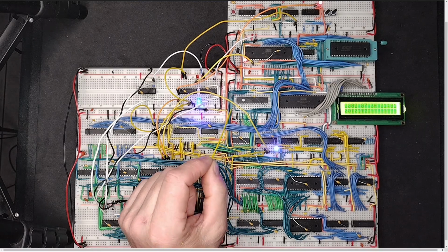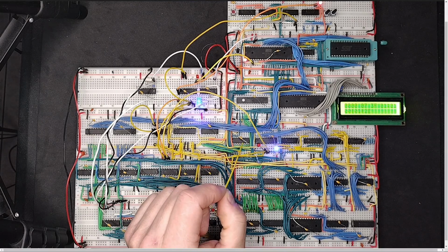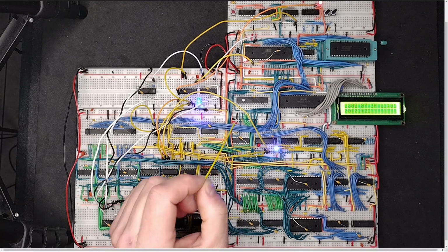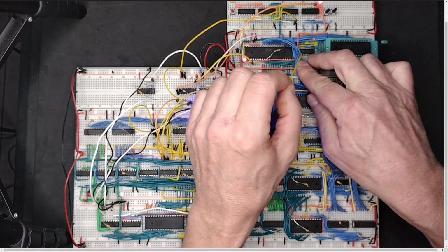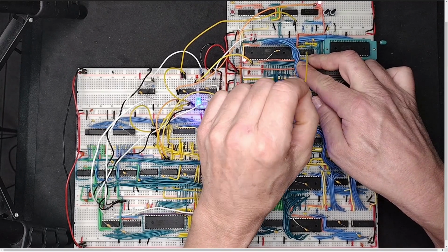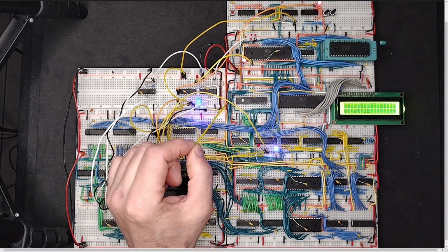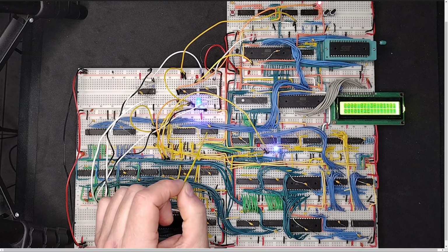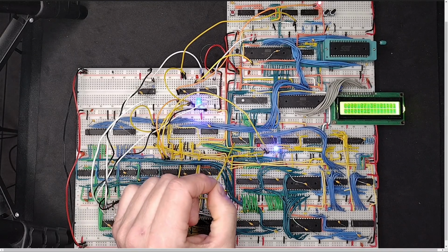But this one, I wired one of the negative active gates of this address decoder to the read write, so that this is active only when the read write pin goes low. What I did was I ran the read write signal to a spare gate on this original NAND gate from the Ben Eater computer, wired as a NOT gate, so that this wire here is the opposite of the read-write bar signal. This is more of a write-read bar signal. And that goes to this gate, so that this address decoder is only active when reading. This address decoder is only active when writing.